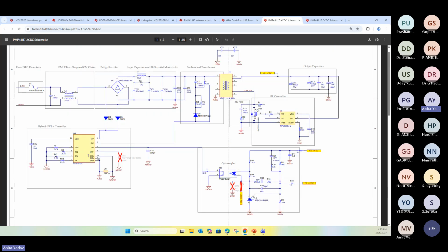And coming to the converter side, there are all the pins. You can see the HV pin is connected to the diode, and the switch node has the 700 volt FET integrated inside. So this is directly connecting to the switch node, and there is a clearance between this, and this device is a QFN package. On the FLT pin, we have the NTC, negative temperature coefficient resistor, so we can configure it according to what temperature. If the peripheral temperature in the design reaches, let's say, 100 or 105 degrees, accordingly we can design the value of this resistor.